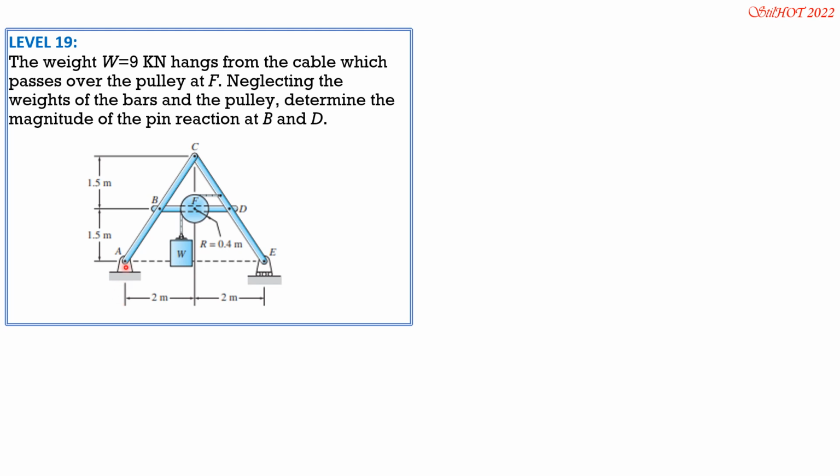So we will call the horizontal component of reaction at A 0 because there's no inclined load considering the entire system. And the vertical reaction at E, because this is a roller support, is R sub E. Summation of forces horizontal considering the entire system is 0.